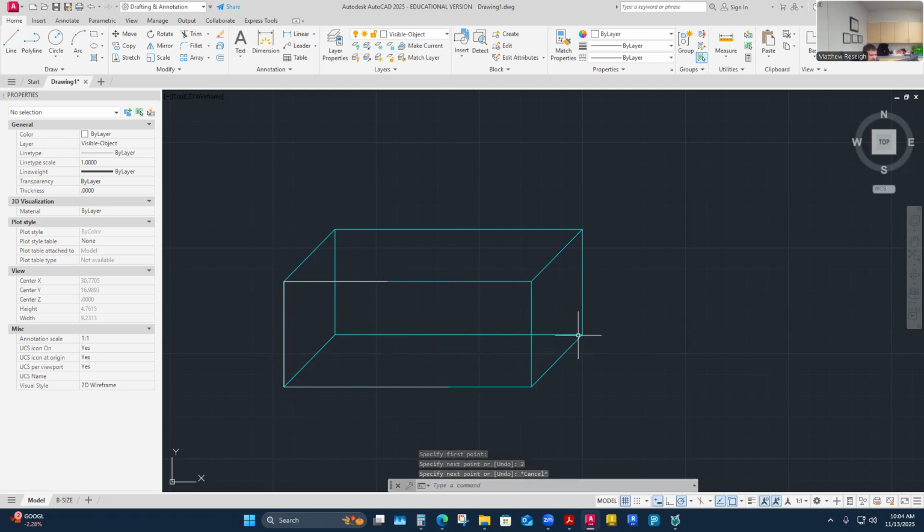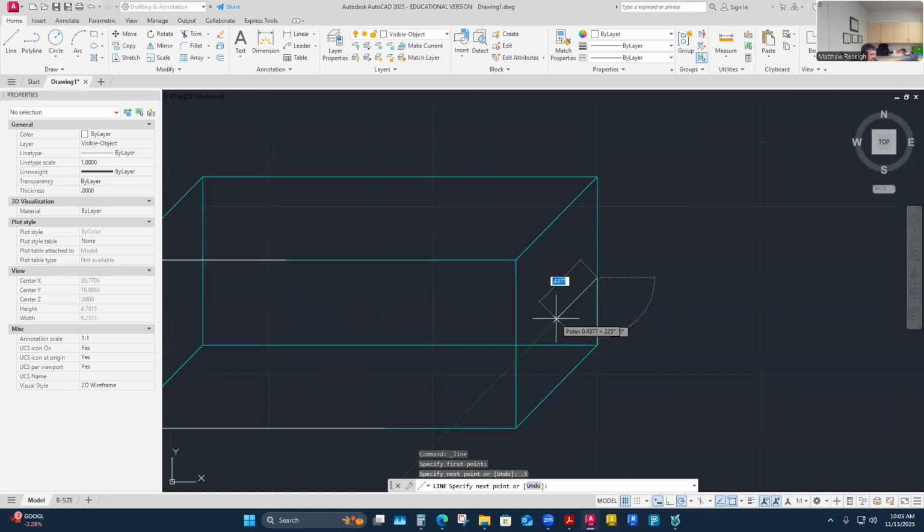Just that start. And let's see if I can figure out maybe the right side view here. No really right or wrong way to start this. I feel like for me, got a little bit of the front view in, maybe I'm going to work on some of the right side view at half depth, but normal height. So really, this little chunk would be up a half inch, and then it's going to come back at me at a 45. Doesn't come clear over to here, but maybe I'm going to draw it over here for a minute just to hold the place. It actually comes up here. 1.25 is as far as it comes to me, but it's going to be half of that.